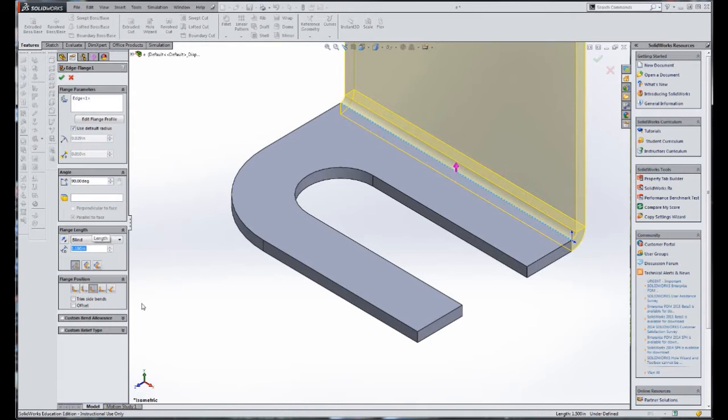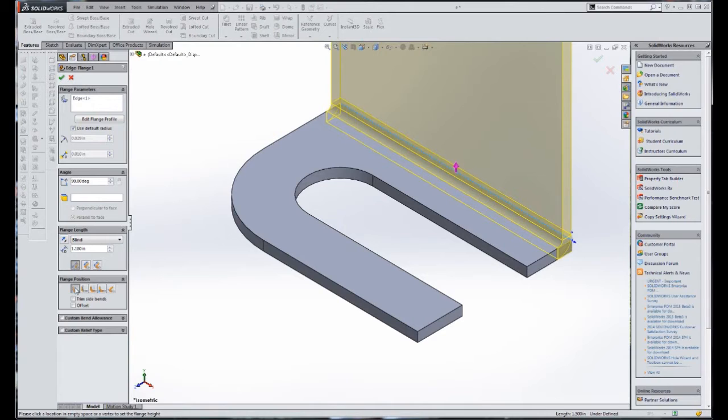And then the type of bend. Well, again, we know that from here to over here is 1 inch, and this back edge needs to be there. So if I move these, you can see now that this back edge is in line with that. And the other thing is, the 0.29 represents roughly half the thickness. It's a good rule of thumb to always use half the thickness.